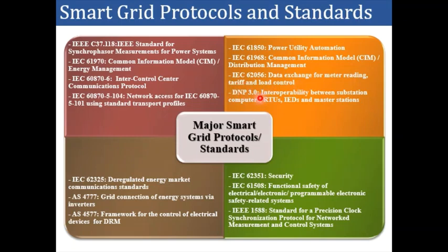Then we have DNP 3.0, which is again similar to 60870-5-104 and 60870-5-101. That means that we will utilize it for the SCADA related data communication. So in this course, we will mainly concentrate on transmission and distribution system protocols and standards.